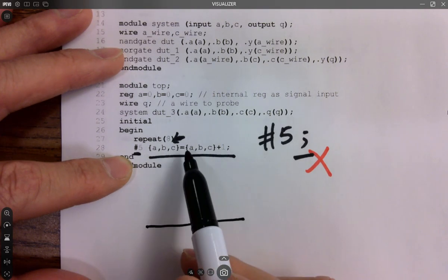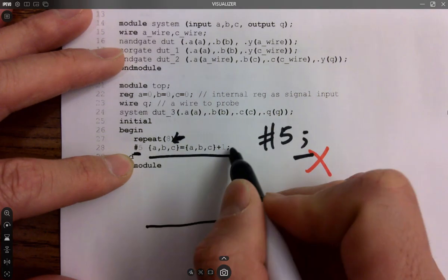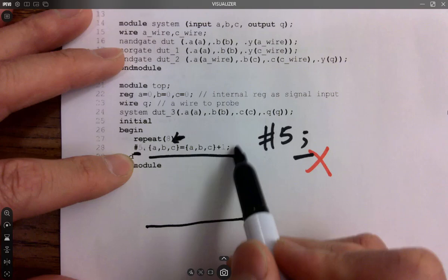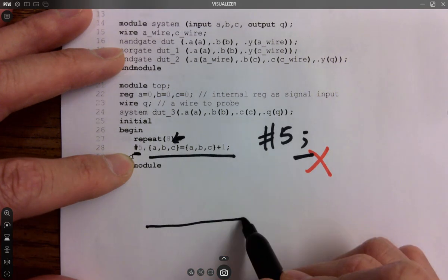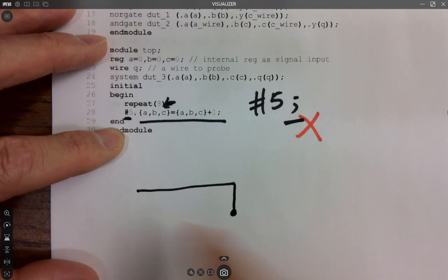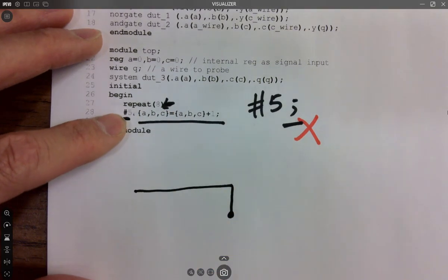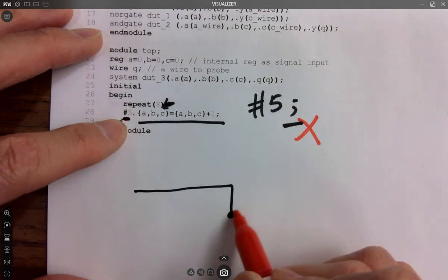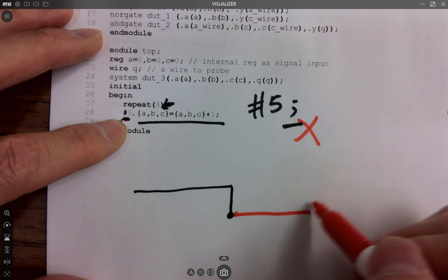So for example, after this addition, the value gets changed. Because there's no time delay for this single statement, it's only making a change to the final output. So eventually it's just one point. Which is fine, because next time when it repeats, it's going to add this 5 nanosecond time delay to extend that point and make another change.